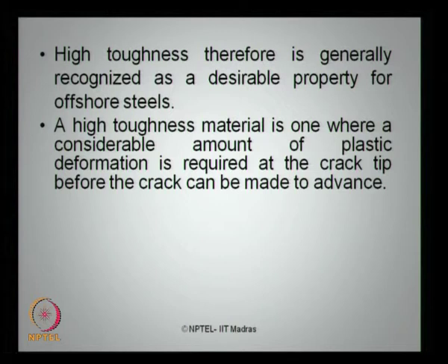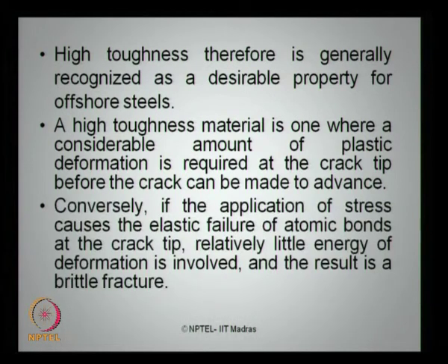High toughness material is one where a considerable amount of plastic deformation is required at the crack tip before the crack can be made to advance. Conversely, if the application of stress causes elastic failure of atomic bonds at the crack tip, relatively little energy of deformation is involved and this results in a brittle failure. So, it is very important to understand the CTOD characteristics also as one of the considerations for selecting material which